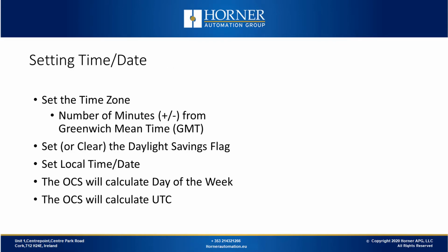You'll start by setting your time zone. That's the number of minutes plus or minus from Greenwich Mean Time. Next, we'll either set or clear the daylight savings flag. I'm going to set our daylight savings flag to be on.